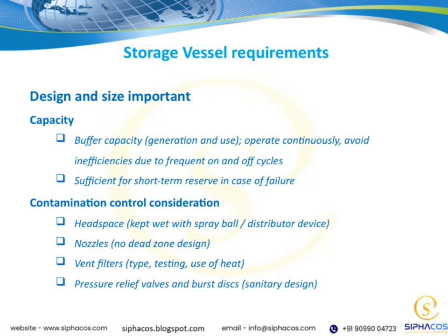Nozzle design is also critical. They should be designed to avoid dead zones where material might stagnate or contaminate. Vent filters play a role too. They need to be chosen carefully, tested regularly, and used with heat to prevent microbial contamination from entering the system. Pressure relief valves and burst discs should be of sanitary design, meaning they are constructed to prevent contamination and facilitate cleaning. Lastly, storage vessel requirements are equally important.